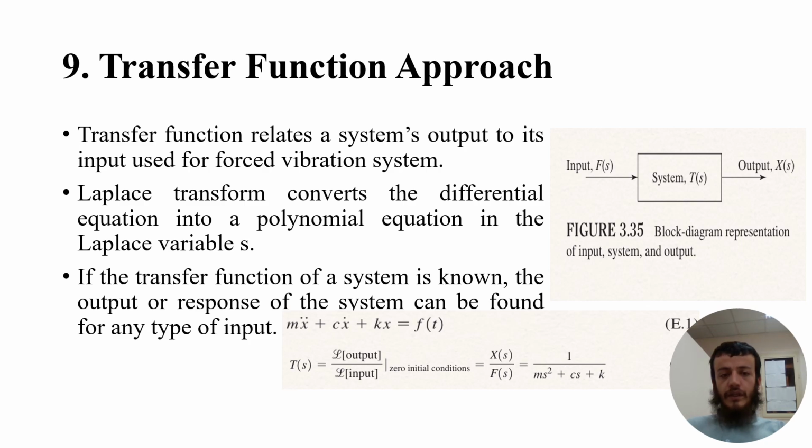The transfer function approach is a good approach to get the response of forced vibration systems. The transfer function converts the differential equation into a polynomial, algebraic equation that leads to very easy solutions. If the transfer function is known, the output response can be found easily. This is a block diagram representing the input system and output system. We have the input as F(s), the system as the transfer function, and the output as displacement here.